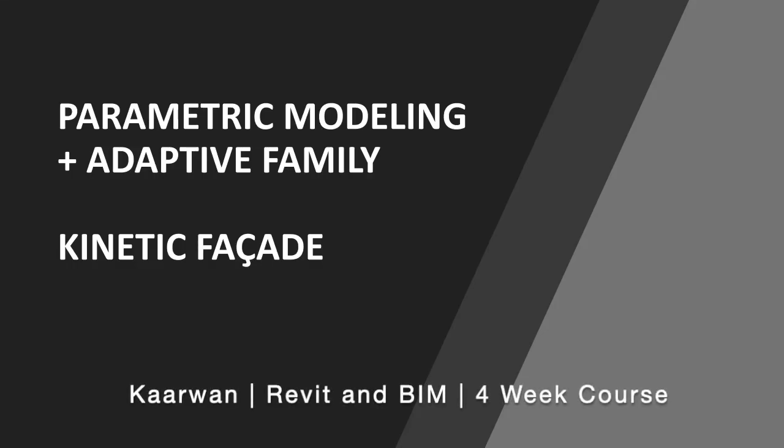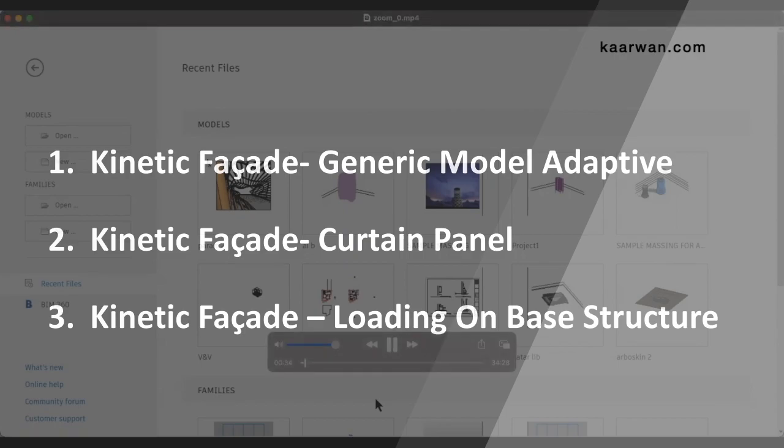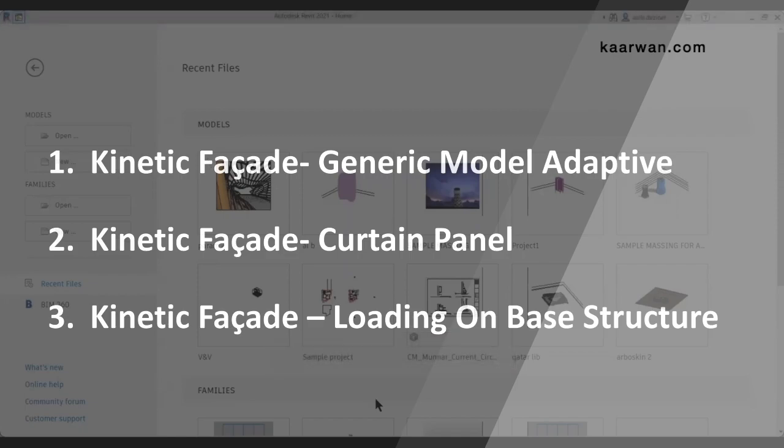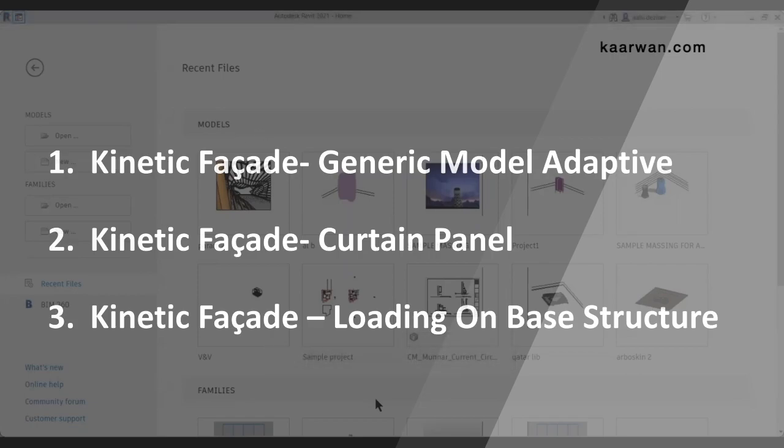Hello everyone. Today we are going to learn to model a parametric facade, a kinetic facade, using parametric modeling and adaptive families. We are going to perform this task in three parts. The first part would be about creating the basic family in a generic model adaptive family template. The second part would be about loading that generic model adaptive family onto a curtain panel pattern based family. And the third part would be about loading that curtain panel pattern based family into the base structure.